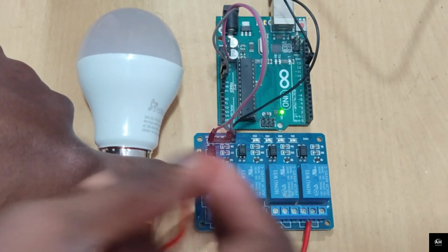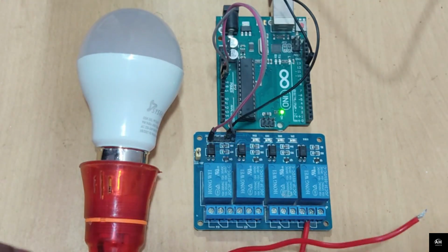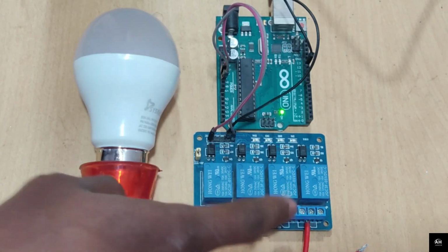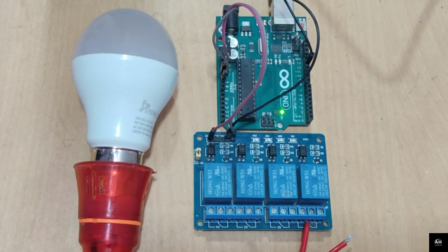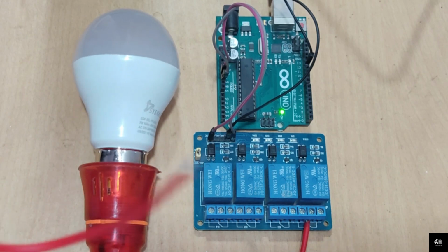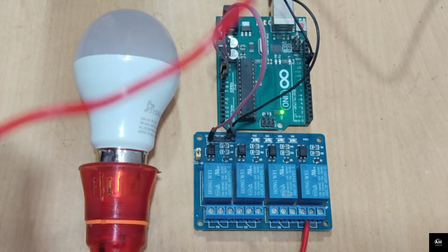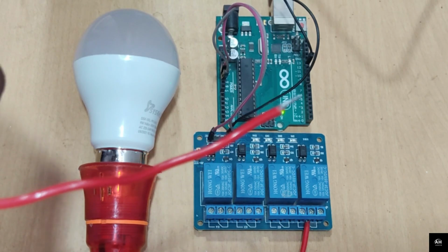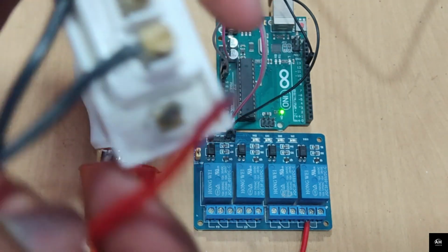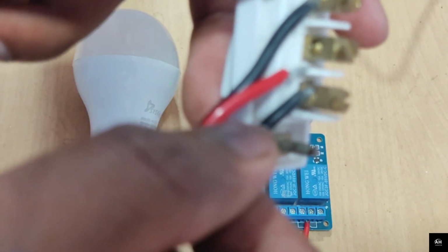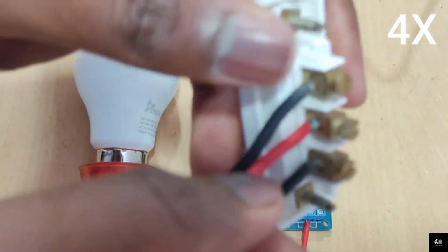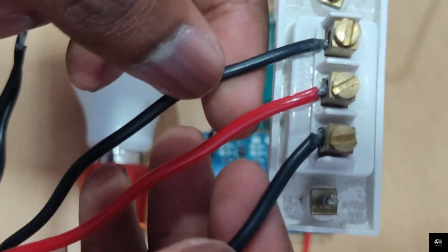Now we will just remove this last cable. And you can see I have removed this cable from here, and the only cable which is connected is the middle cable which is coming from our bulb, and I have removed the cable which is coming from our switch, which is our main socket through which we are connecting the power. So we will be inserting it inside this two-way switch in the middle input of it.